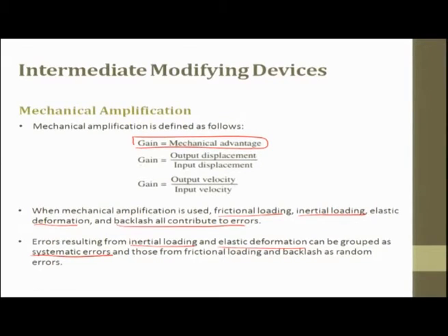So, if we can figure out the response over a period of time, then accordingly the correction factor can be given. Systemic errors are nothing but, if you go back to precision and accuracy, somebody trying to fire all the bullets at one point: they are very accurate, but they are displaced from the center point. So, you can put a systemic correction, and then move this to this point.